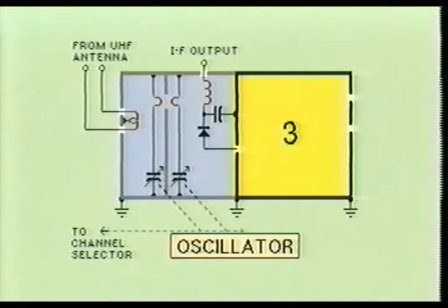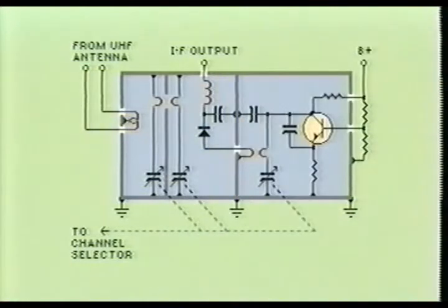The third compartment contains the UHF oscillator circuitry. It is basically a modified form of the Colpitts oscillator configuration called the Ultra Audion. Notice that this circuit uses the silicon epitaxial planar transistor as the primary active component of the oscillator stage. This stage also contains a trimmer capacitor used to adjust the oscillator frequency for channel selection.